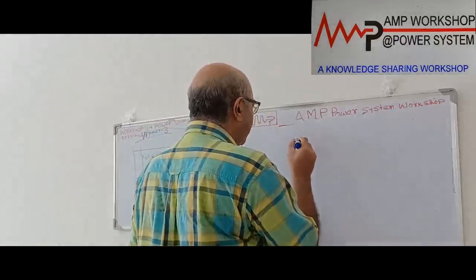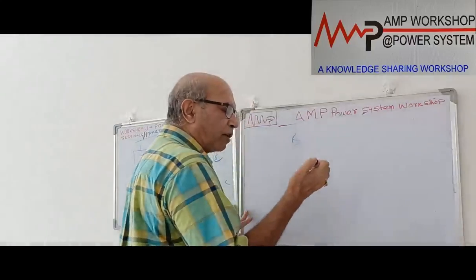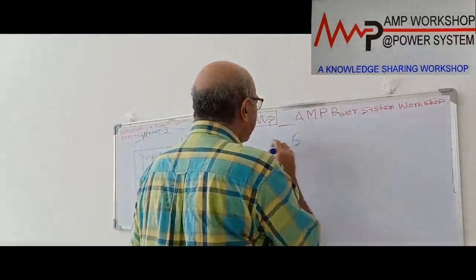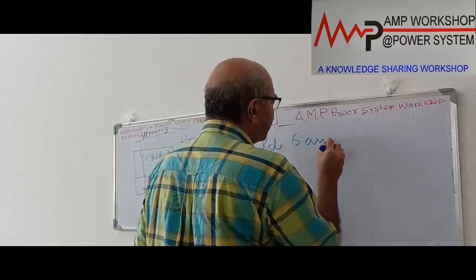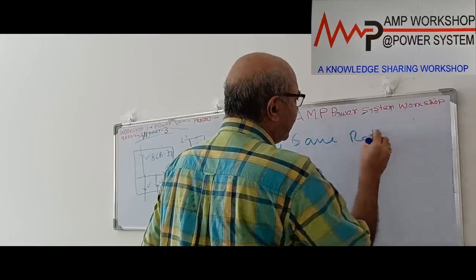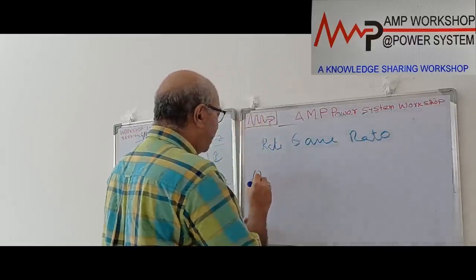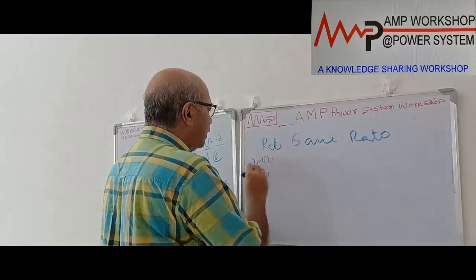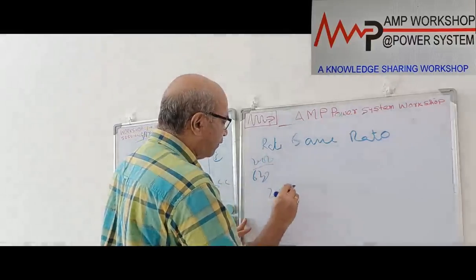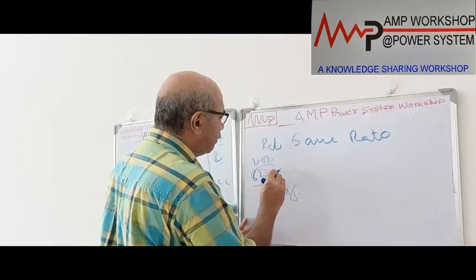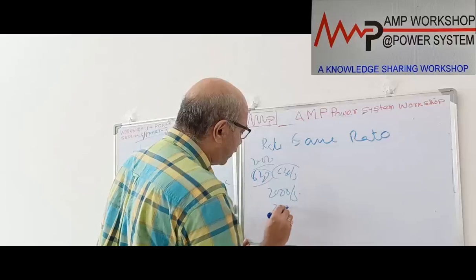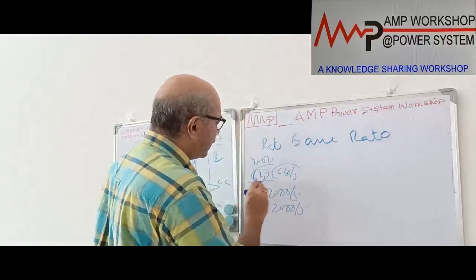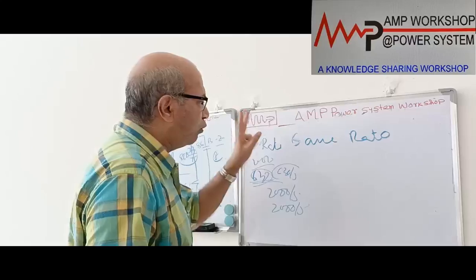In the busbar differential protection, we should not use any auxiliary CT. Okay, CT ratio of all the CTs will be the same. That is one of the basic requirements. Maybe the feeder is 630 ampere, incomer is 2000 ampere. Incomer CT is 2000 by 5. Outgoing feeder 630, we generally put 630 by 5. But in case of differential protection, the CT will be 2000 by 5 for the 630 ampere breaker also. So all the CTs will be of identical ratio.